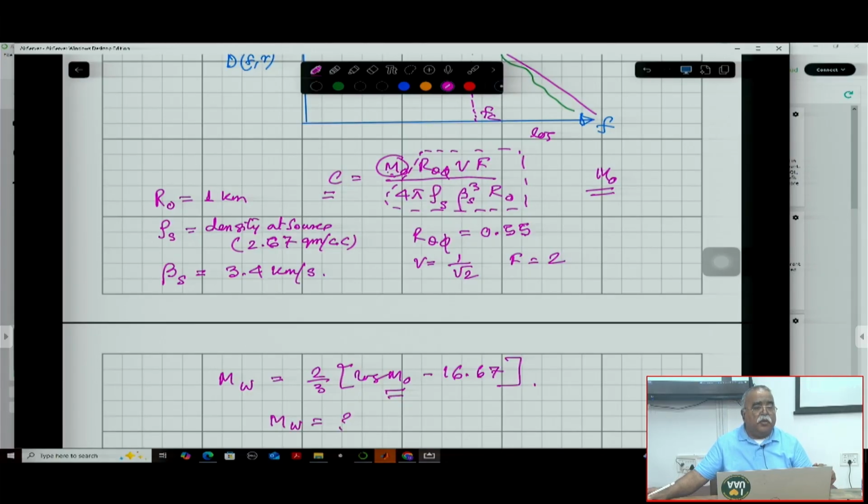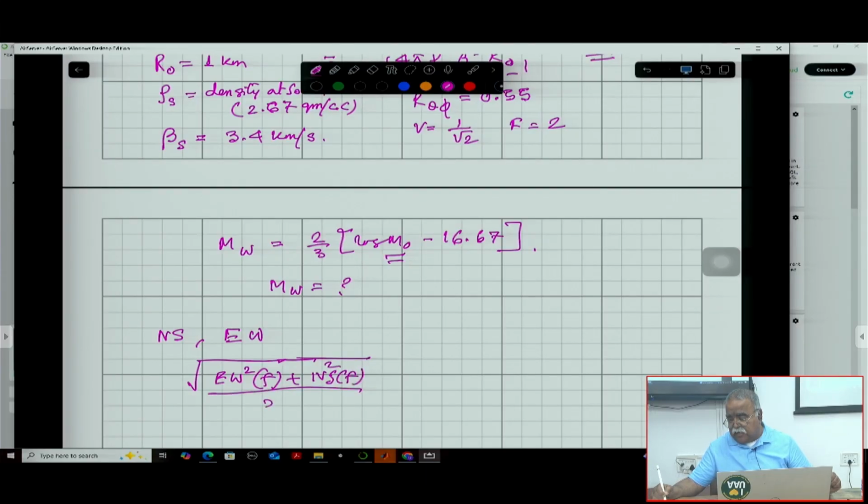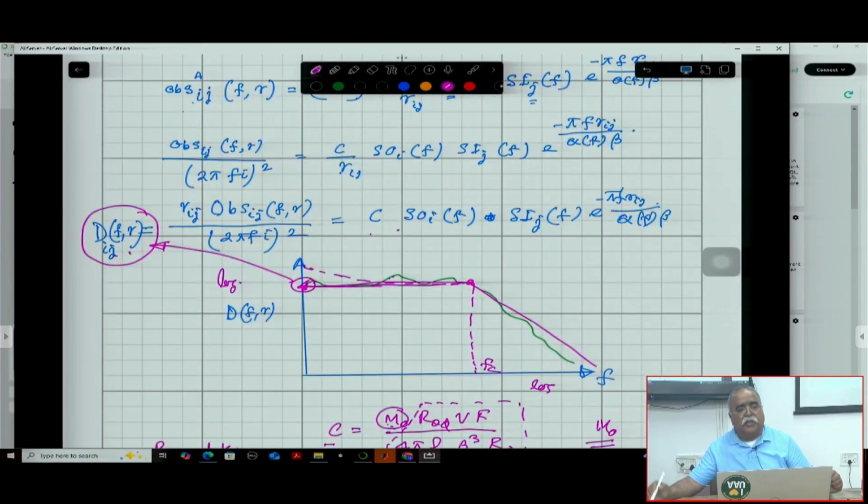Okay. So before doing that, you first calculate the acceleration spectra, for both the north-south component and the east-west component, and calculate the average of these two from the acceleration spectra. Okay. So make it an average horizontal. This is the average horizontal spectra, and from that average horizontal spectra, you can do this part.